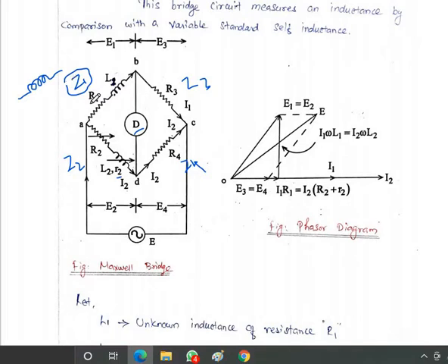Okay, but here the resistive load and inductive load are both connected in series, so the resistance also drops some voltage, and the inductance will oppose the current. It is an opposing property, so some voltage will be dropped here. So both resistance and inductance will be taken into account, so it should be represented as an impedance.